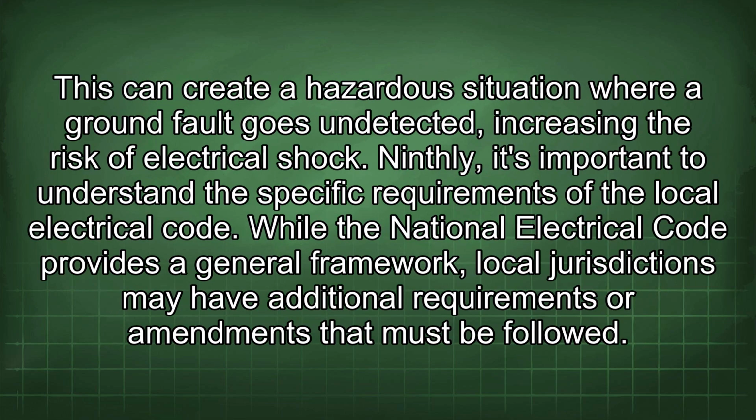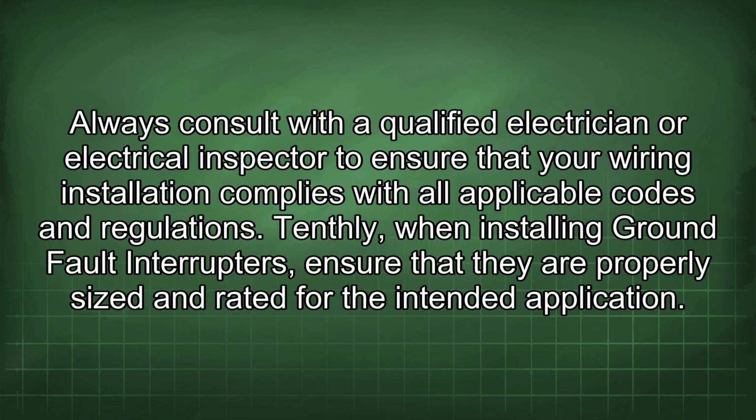This can create a hazardous situation where a ground fault goes undetected, increasing the risk of electrical shock. Ninthly, it is important to understand the specific requirements of the local electrical code. While the National Electrical Code provides a general framework, local jurisdictions may have additional requirements or amendments that must be followed. Always consult with a qualified electrician or electrical inspector to ensure that your wiring installation complies with all applicable